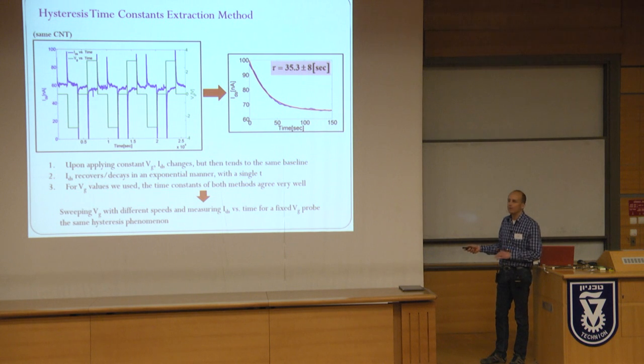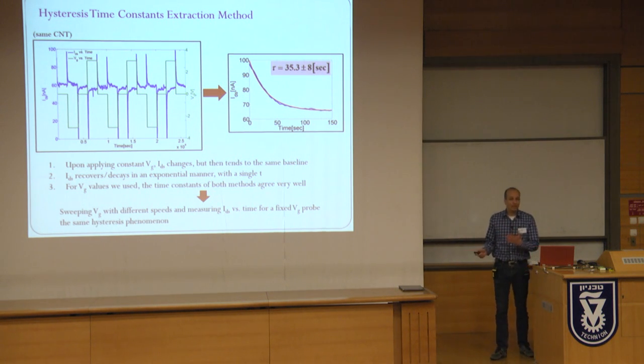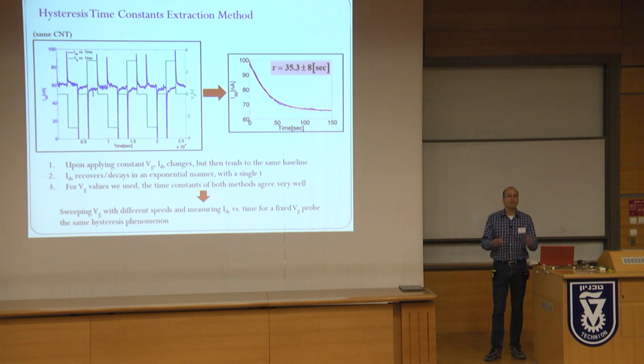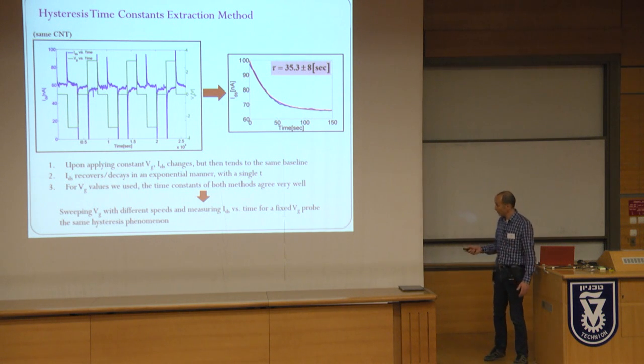to the nanotube current. And this is, for example, a zoom on one of these, so you can see very nicely how you have this decaying. And apparently, surprisingly, the decay is almost the same time constant. The reason is very simple. If you do the IV characteristics, or as a function of time, you sense the same phenomena. There's some hysteresis, there's some origin for this hysteresis, and you can sense it however you wish.